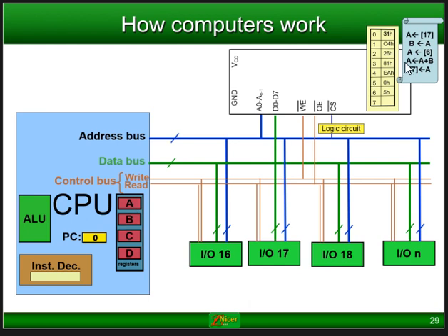That's what this instruction means then, which is the 81 supposed to be. Add the two together and place the answer in the A register. So we'll see how this executes. And then finally, this at address number 4 means take the contents of A, which is sitting in A, and go and place it at address number 7. Now address number 7 is actually this one here. So this is what it means.